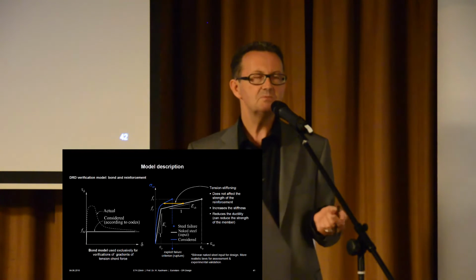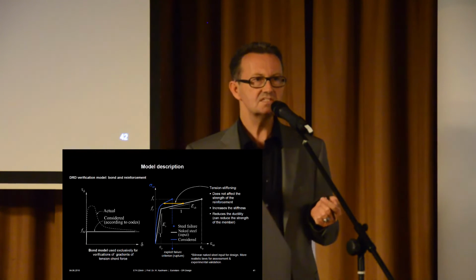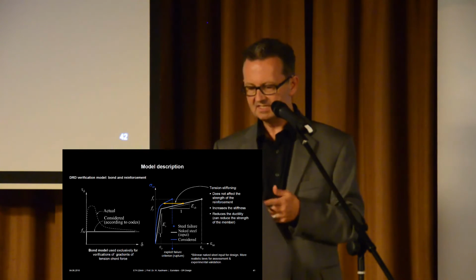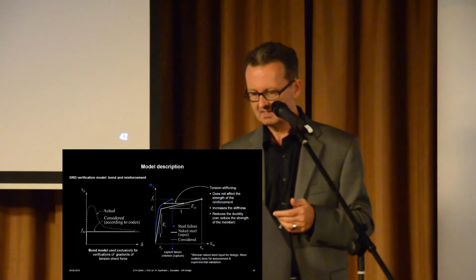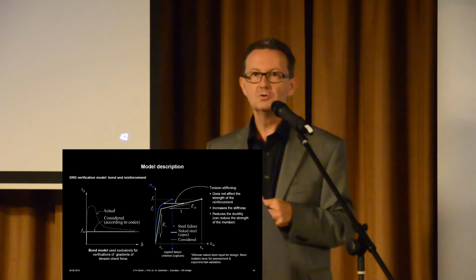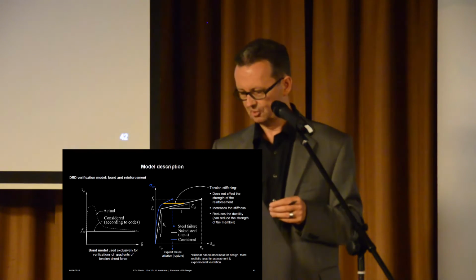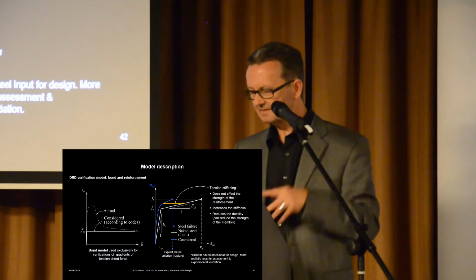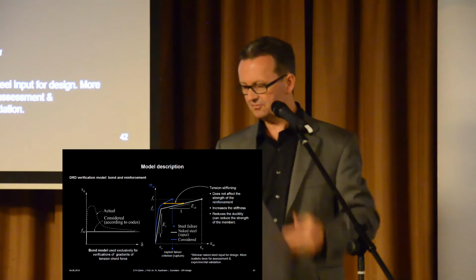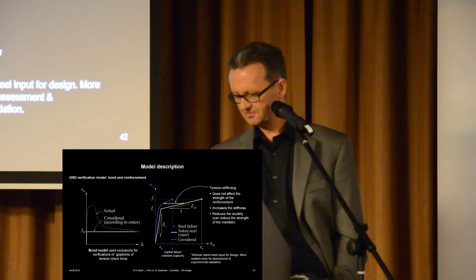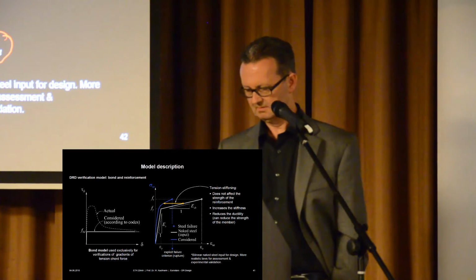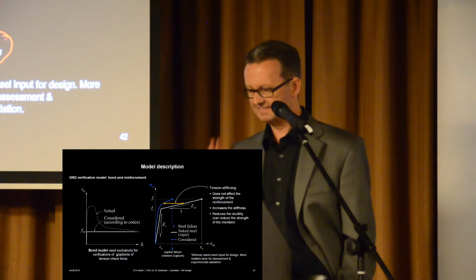And there what we did, we back calculated the bond stress that corresponds to the anchorage length in the codes, and we are using this as a constant value for anchorage problems along the rebars, if you have a gradient in the tension cord force. And in between, to model the tension stiffening, we use such curves that relate now the average strain to the maximum stress at the cracks, sigma_sr. R is at the crack.